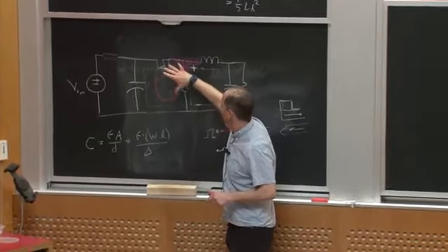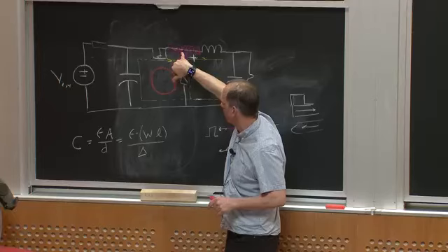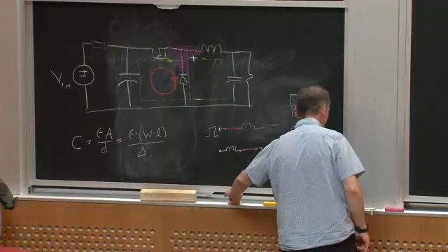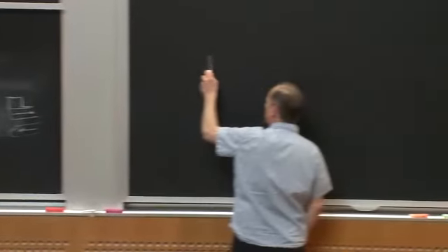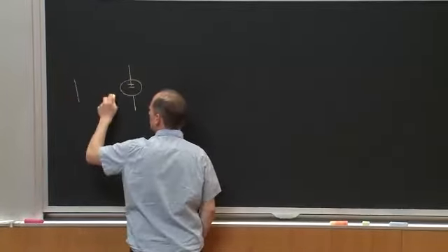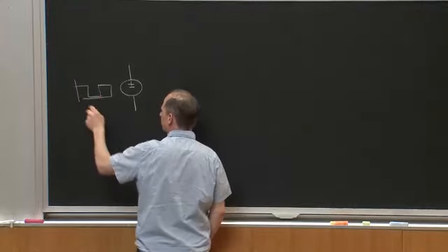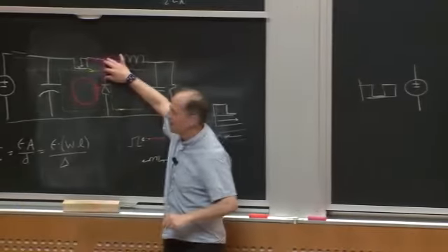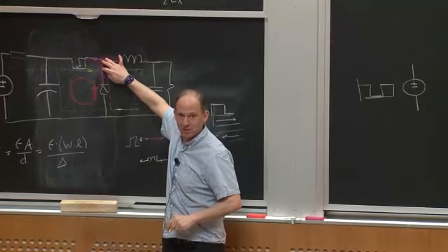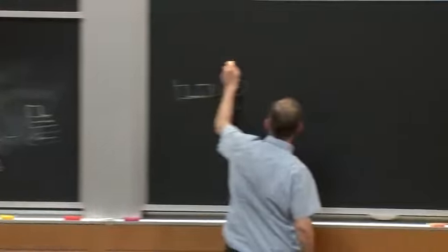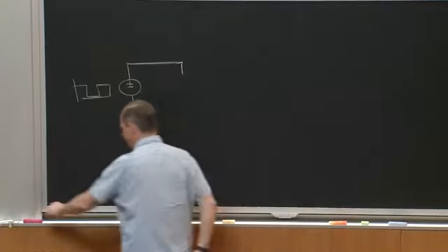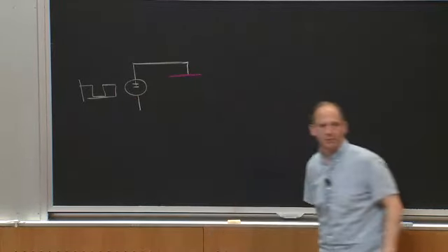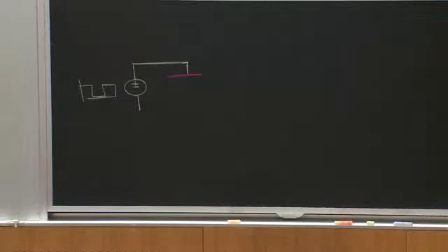So let's just imagine this node is driven by the switching, so there's sort of a square wave voltage here, right? If I thought about modeling this, I might say, okay, here's my big square wave voltage, going up and down like this, okay? And this piece of metal here forms one plate of a capacitor. What's the other plate of my capacitor? Well, it depends what's around it.